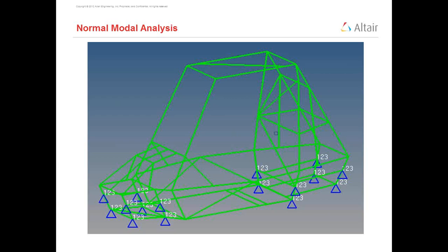And then we will see the different modes due to the frequency in hertz. We will take the range as frequency from 1 hertz, that is the minimal frequency, to a range of 200 hertz, and then find out the different mode shapes. We will find the first 10 mode shapes and then conclude that the maximum should not go beyond 100 hertz.